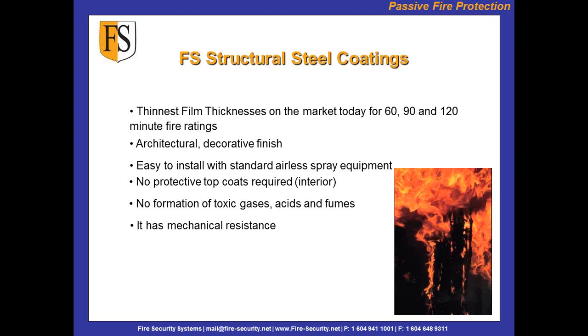I mean, there's even fingernail tests. You can scratch the surface of it, and if it's not fully cured, that will sink in. Once you breach the surface, the upper crust, if you want to call it that, you want to see if you can get to the bottom of the steel. And obviously, if you do a scratch test, it's a very easy patch up because you're only patching that section. But yeah, you can do a hammer test or a surface scratch test, and that will show the cure rate. Okay.